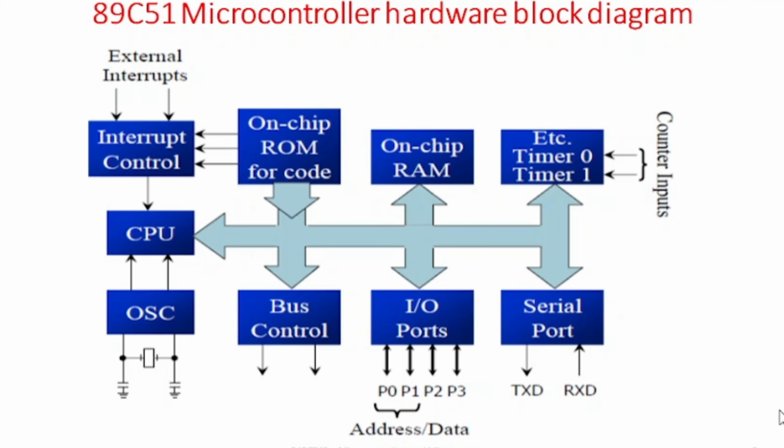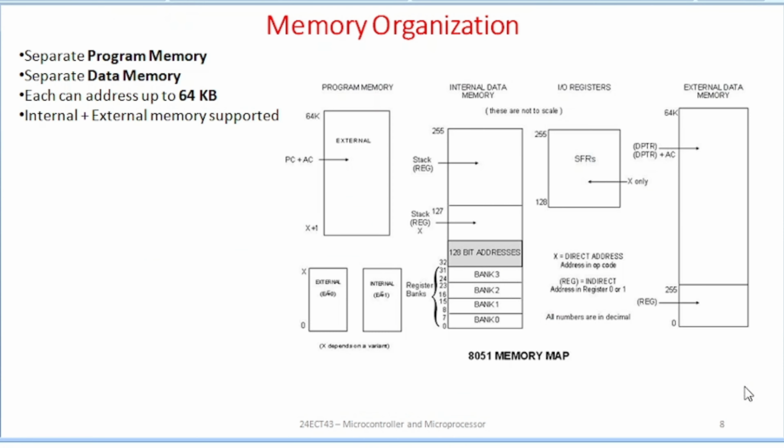The memory organization in the 8051 architecture provides on-chip memory expansion capabilities, which supports physical address spaces whose functionality is separated at the hardware level by different addressing mechanisms used for read and write control signals or both. These are for accessing the internal program memory, internal data memory, external program memory, external data memory, and on-chip special function registers.